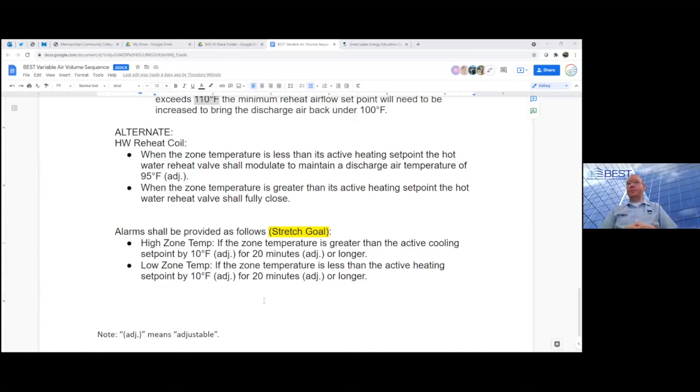When we're looking at these alarms and at occupancy, we aren't actually connecting to a system. You're just going to use whatever points are appropriate for your system, probably a Boolean writable on your occupancy and possibly Boolean writables for your alarms as well. We're not going to send them up to a system or go through the effort of making them a real building alarm. That's much more involved.